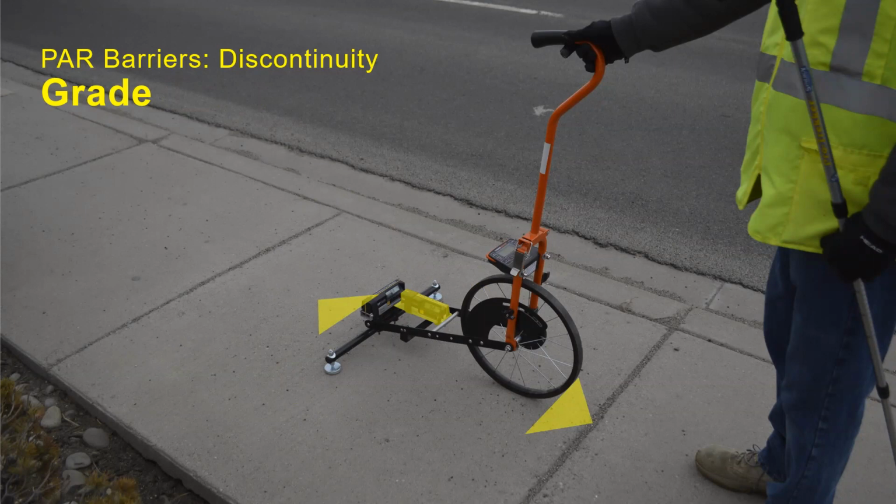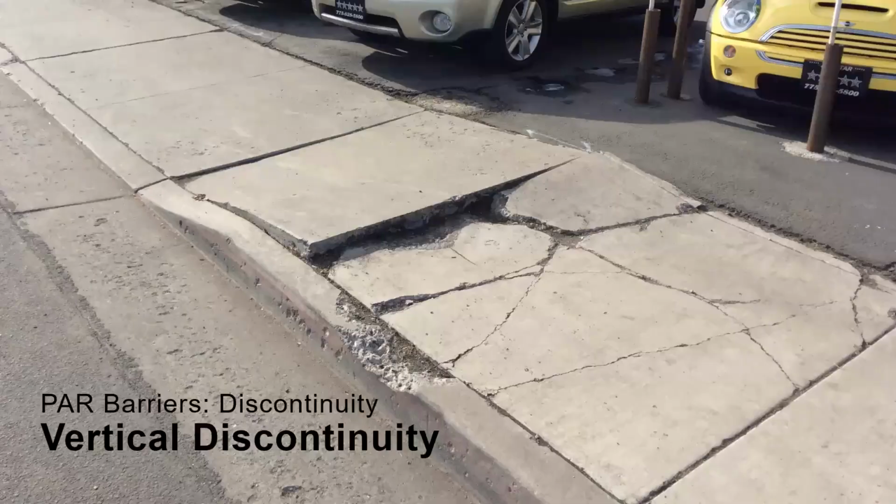Grade is simultaneously measured using the level position parallel with the path of travel. Using the app sidewalk assessment process, grade and cross slope are entered as feature points with distance to indicate the length of the non-compliant segment. When the sidewalk grade exceeds that of the street, as is the case in this image, and the sidewalk exceeds a maximum running slope of 5%, the grade is non-compliant.